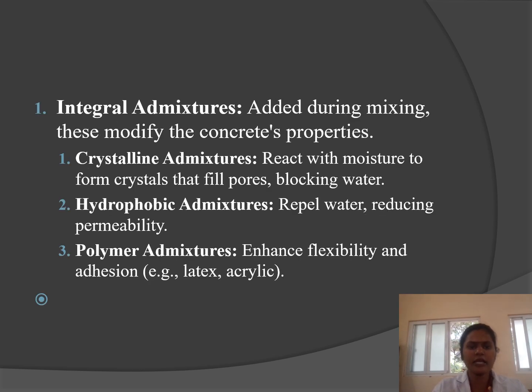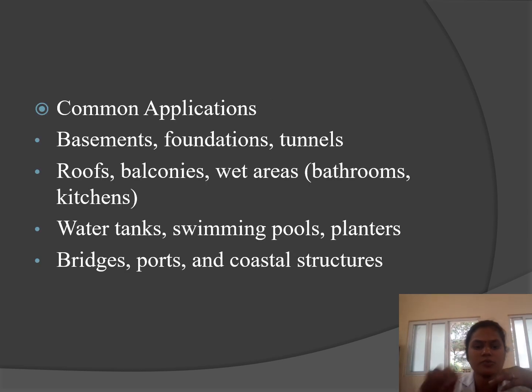Next, integral admixtures, added during mixing. These modify the concrete properties. Crystalline admixtures react with moisture to form crystals that fill the pores, blocking water. Hydrophobic admixtures repel the water and reduce the permeability. Polymer admixtures enhance flexibility and adhesion. Example: latex, acrylic.